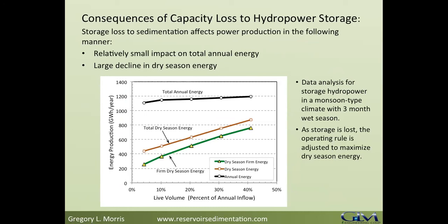It's a sediment-free environment created by the presence of the dam, and it's only a temporary condition because the dam will eventually fill with sediment, and once filled, the sediment will again start moving downstream.